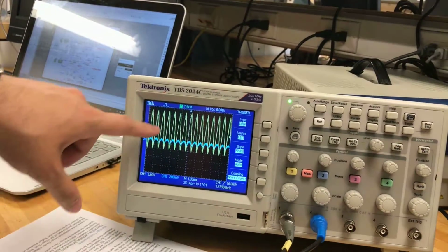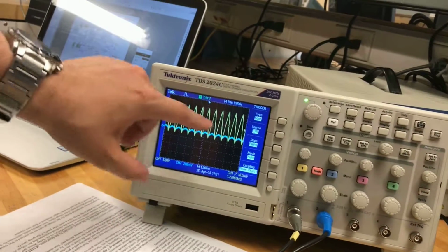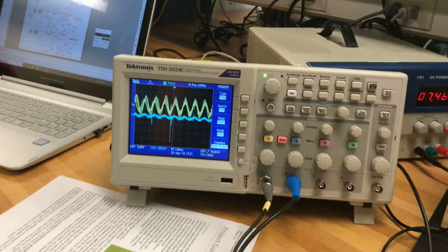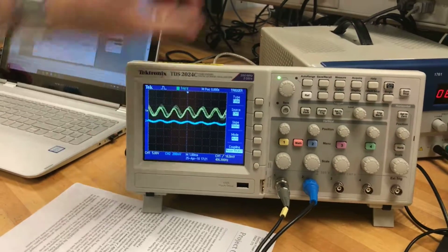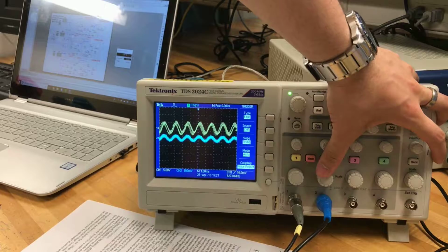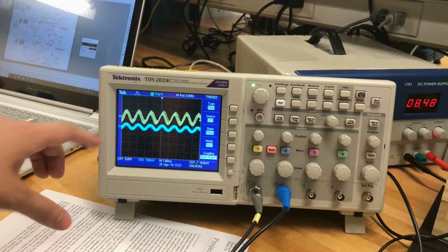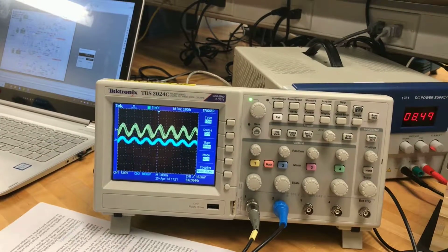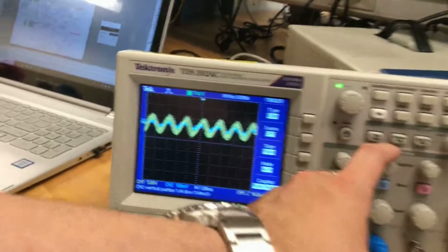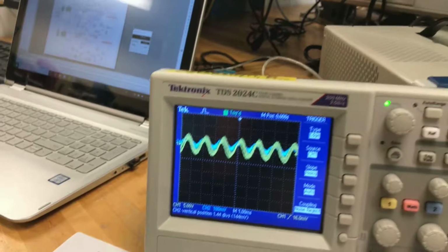The voltage is very high and our phase is just slightly out of phase. Now if we were to correct it, everything pops back. The sizing is a lot better for the difference in the balance between the voltage and the current, and you can see our phase is virtually the same, as the peaks are very close to each other. And this is the 98 power factor which we have.